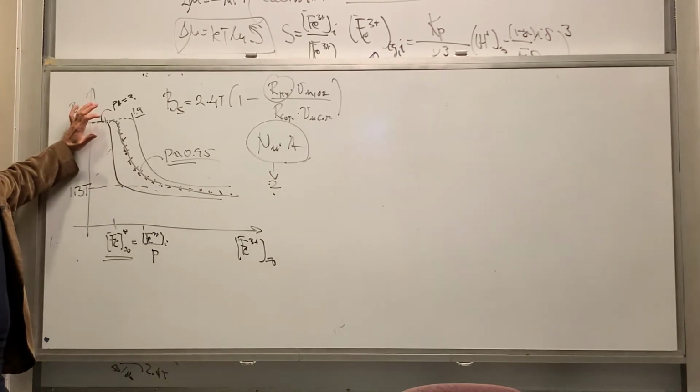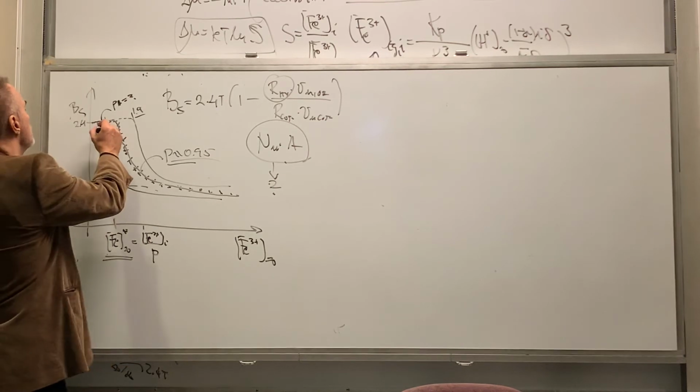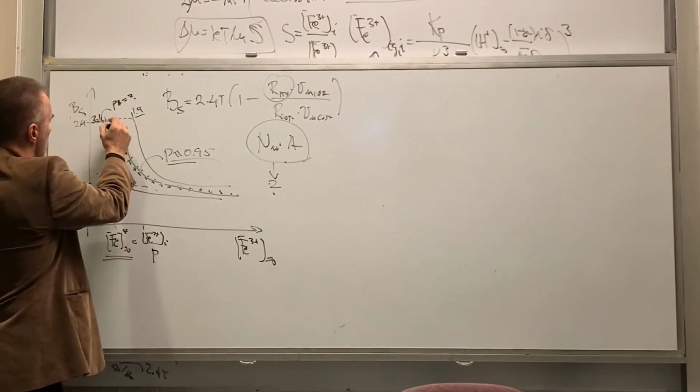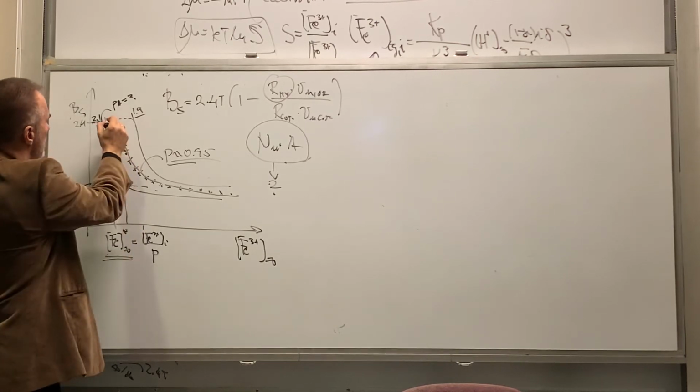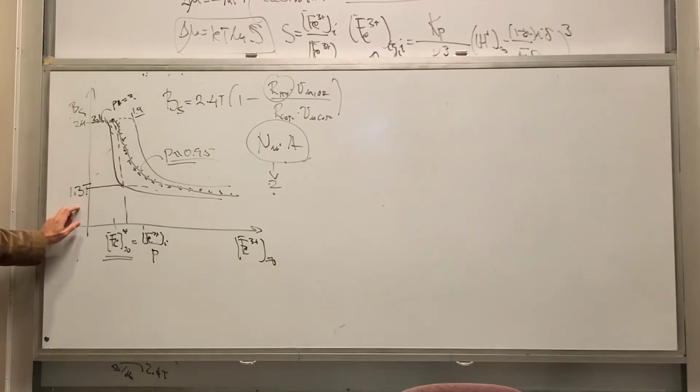But if my pH probe gives me wrong reading, and instead of 2, I'm reading it's 2.1, and I think I'm here, and I think I'm doing okay because I should be getting 2.4, guess what happens? I'm here. None of the devices is good. Okay?